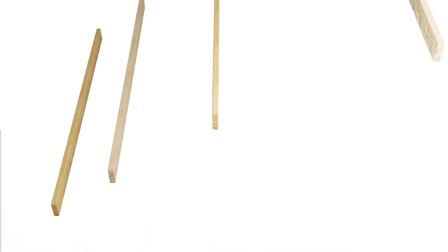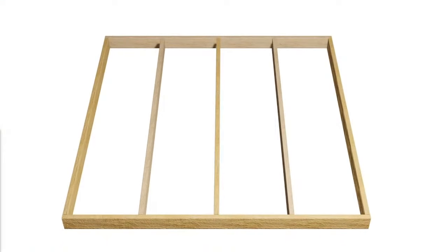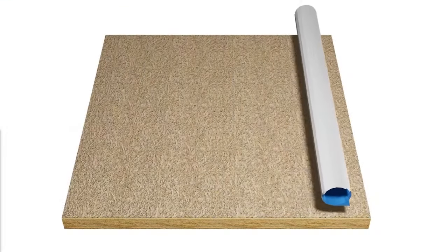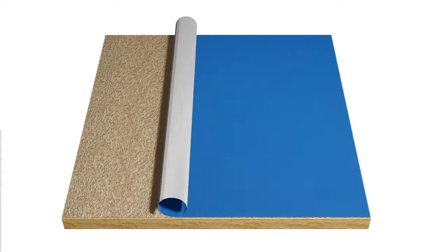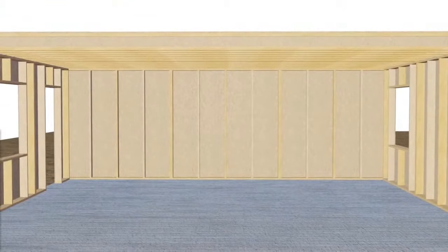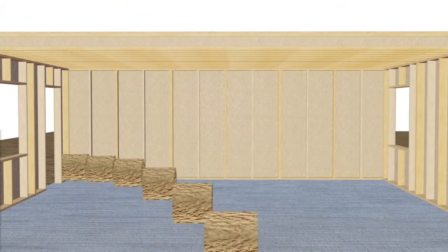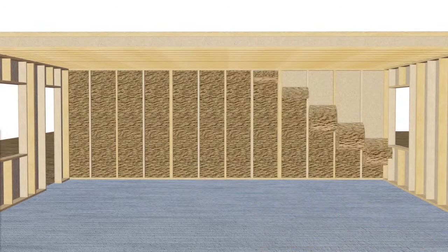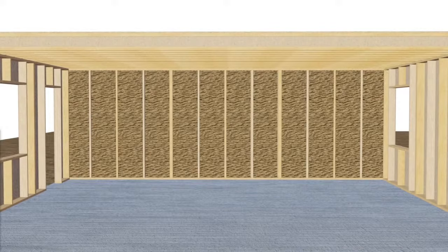Another type of structure used is timber frame, and this is the most common method used in the construction of kit homes. Homes of this type use timber panels and floor cassettes constructed in factories, which are delivered to site and then can be erected very quickly. This gives a basic wind and watertight structure comparatively quickly, and the building can then be fitted out with services and finishes. Things like insulation are usually added after the building structure is up, in what's called open panel construction, but sometimes the insulation is factory fitted too in a closed panel frame.